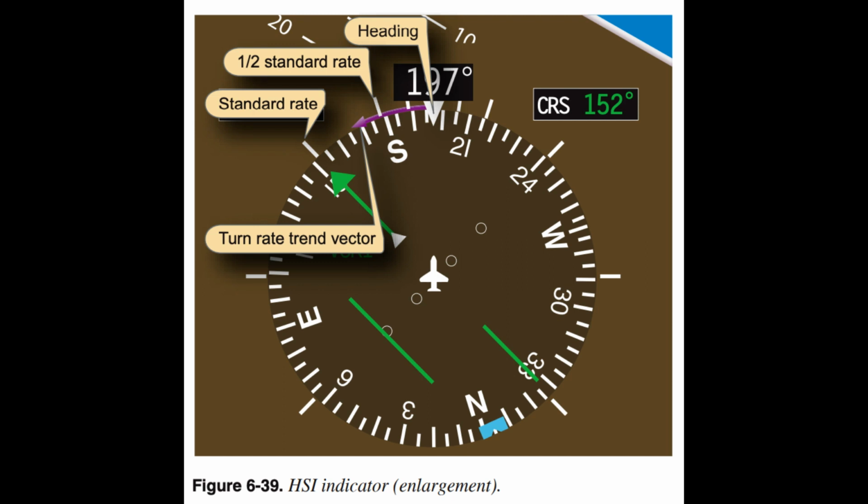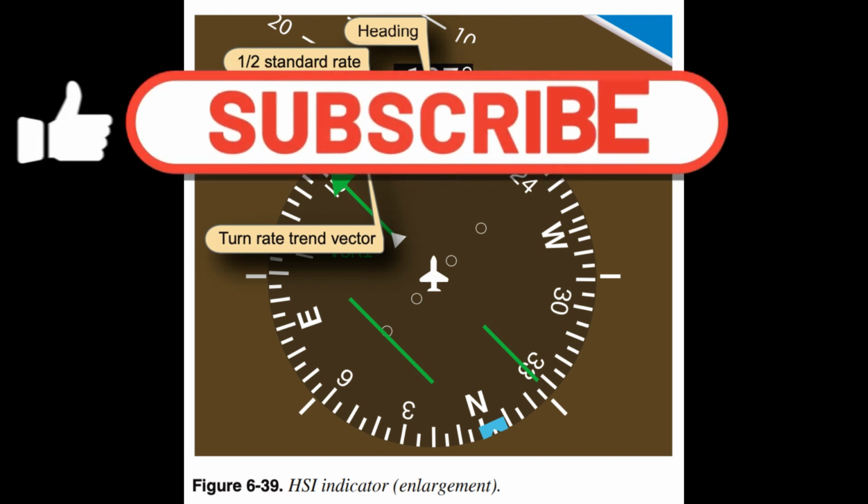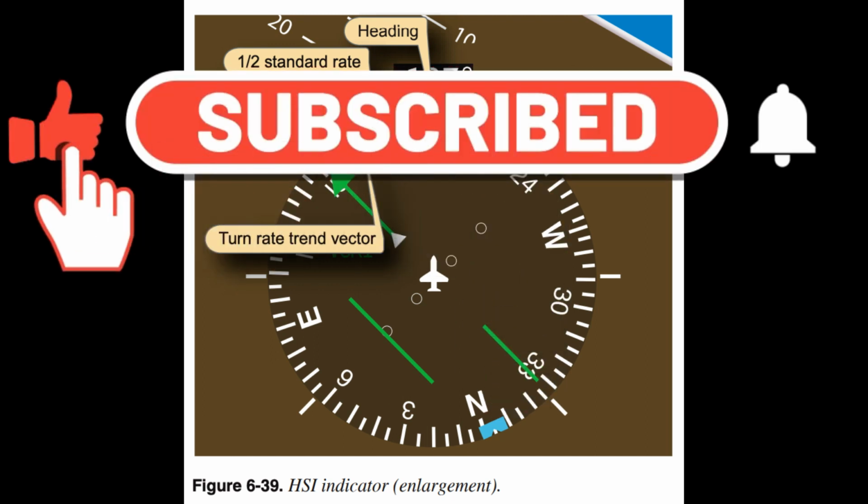Emphasis. In initial training, placing emphasis on a single instrument is very common and can become a habit if not corrected. When the importance of a single instrument is elevated above another, the pilot begins to rely solely on that instrument for guidance. When rolling out of a 180 degree turn, the attitude indicator, heading indicator, slip/skid indicator, and altimeter need to be referenced. If a pilot omits the slip/skid indicator, coordination is sacrificed.